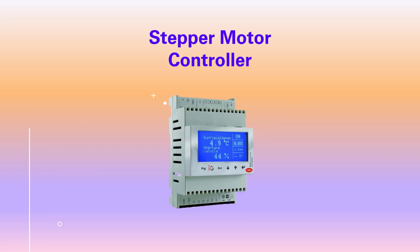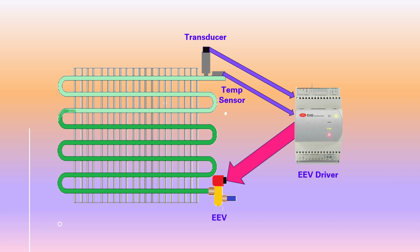Moving on to the EEVs now, we have a stepper motor controller, very clever bit of kit and very efficient, I believe. This shows the setup for an electronic expansion valve. You've got the EEV in the normal place at the entry point to the evaporator. You've got a transducer on the suction output and the temperature sensor, and they're all connected to the driver, and the driver reads the pressure and the temperature and sends out a pulse and opens and closes the expansion valve.